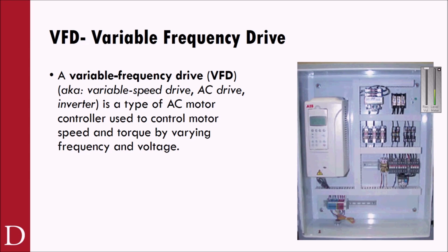What's funny about all of this, and motor starters as well, you might say, oh, for $120 I can get a motor starter, and for $250 I can get 2 motor starters. Now I have direction control, overload protection, I've got all kinds of stuff, right? And that was true when VFDs were really, really expensive. But what I would tell you is VFDs are now comparable.